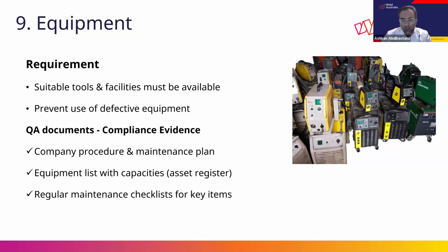So because you are under qualification of the ISO 3834, for example Part 2 or Part 3, you need to provide your own procedures. You can get some idea or information from the client on what you need to include in your procedure, but the final responsibility is with you. And the ISO 3834 certificate reflects your compliance with the quality requirement regardless of your client. You may have this client this year and another client next year. So the procedure needs to be designed by yourself.